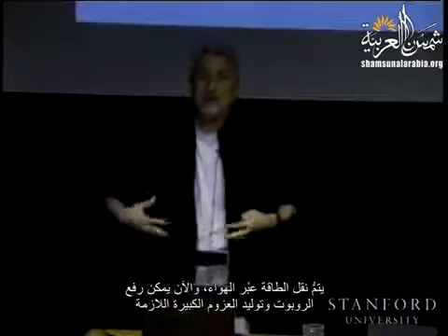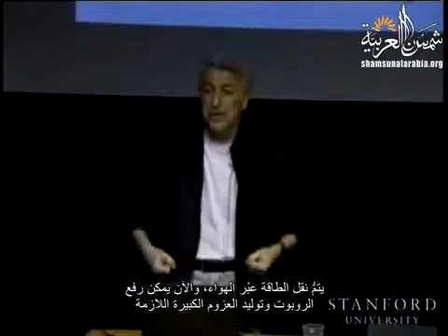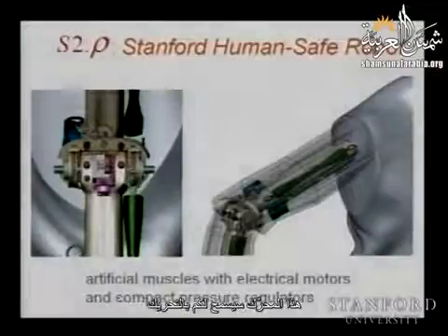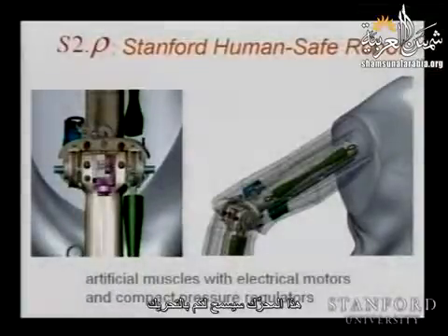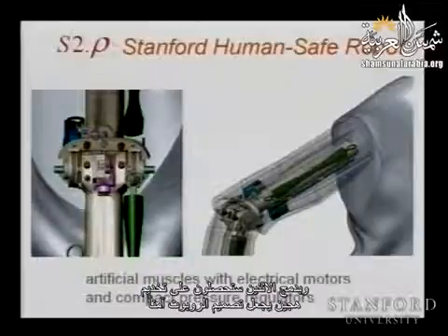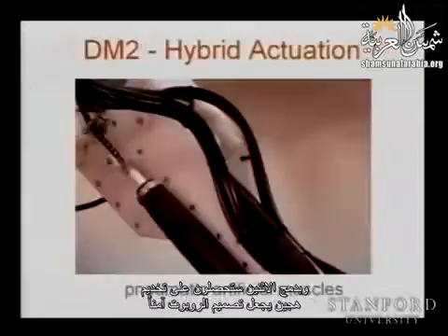You can produce the large magnitude of torques needed. And then you add a small motor on the joint. And this motor will allow you to get the dynamics. So combining the two, you get hybrid actuation that essentially leads to a safe robot design.